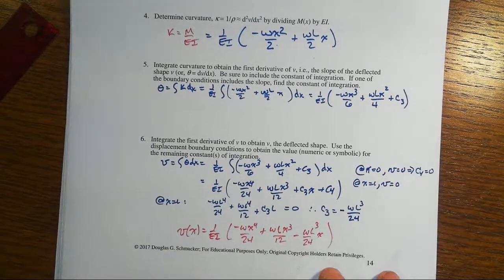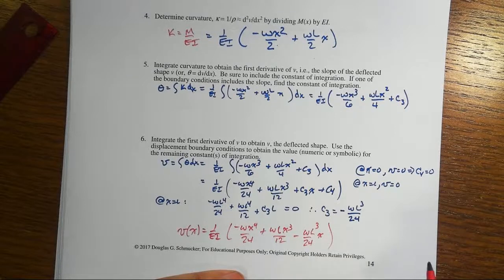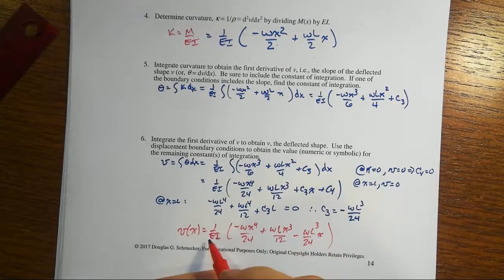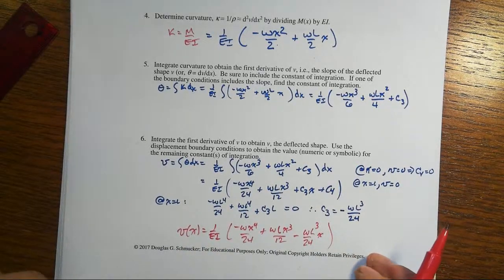Right, now one thing I want to check are units. I get length to the 4th, XL cubed. LX cubed is length to the 4th, and X to the 4th is, of course, length cubed. That's all the same. W has force per length, so force over length times L cubed would be force length cubed over force length squared, right? Force over length squared would be E and times L to the 4th, so that's all FL squared. So FL cubed over FL squared will give me length. That's exactly what it should be.